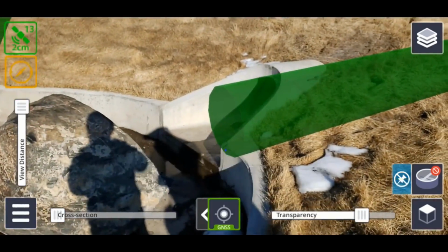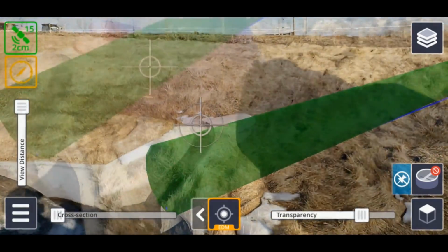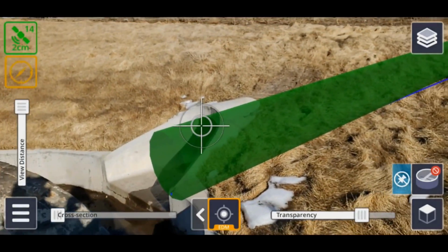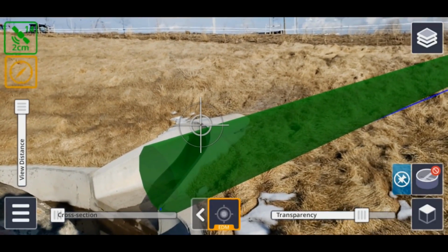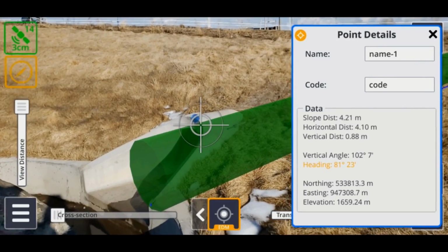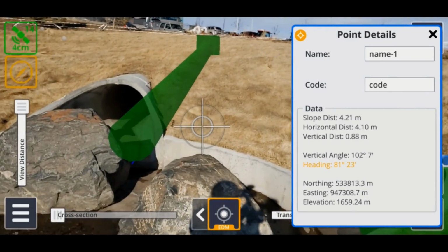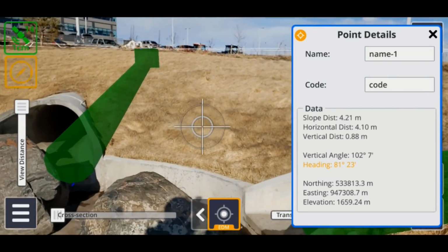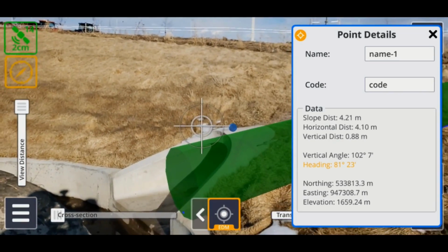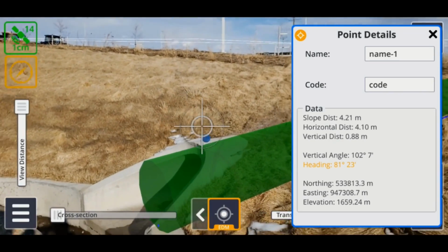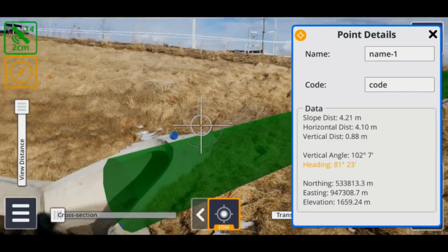The next application we'll take a look at is the distance measurement function, which allows you to measure your position and distance in SiteVision via one of 3 methods: current GNSS coordinates, augmented reality, or the built-in EDM. GNSS will measure where you are currently standing in a global coordinate system, while the AR and EDM modes measure to points on the model and points in the real world respectively. This gives us the distance as well as the bearing and coordinates of the measurement in relation to the model. You can also change the name and feature code of the point for easier reference in the office.